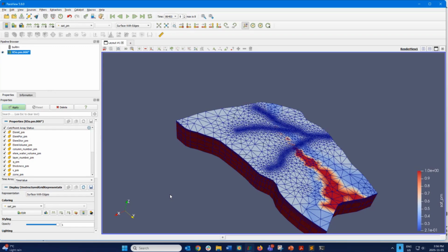First, build yourself a really coarse model, and once you have it well calibrated, you can then create a new version of the model that is more refined, that has higher mesh resolution. Going through the process of calibrating a coarse model and then mapping what you've learned from that coarse model onto a refined model will probably save you a lot of time, because let's say a coarse model takes an hour to run and the refined model takes 10 hours to run.